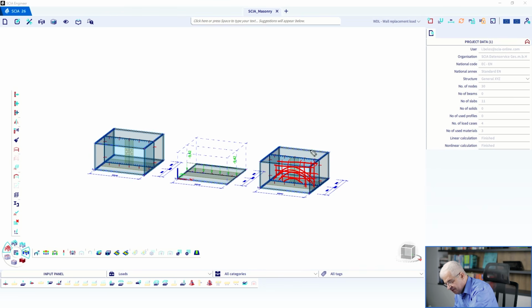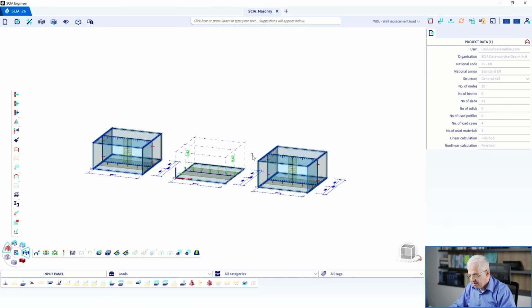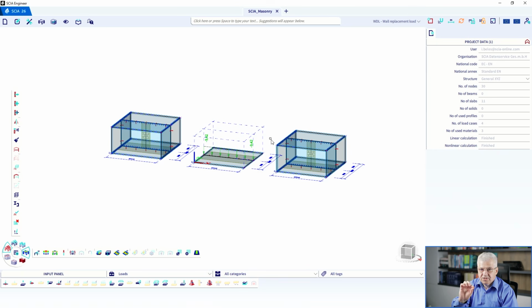But if you have line hinges, then you have maybe only 10 or 20 elements, so the calculation is much quicker, because all elements with tension are deactivated at once. So you get much fewer iterations. So it's calculated. We can compare the results. First, I would like to see the deformations. That's the first thing I want to see.